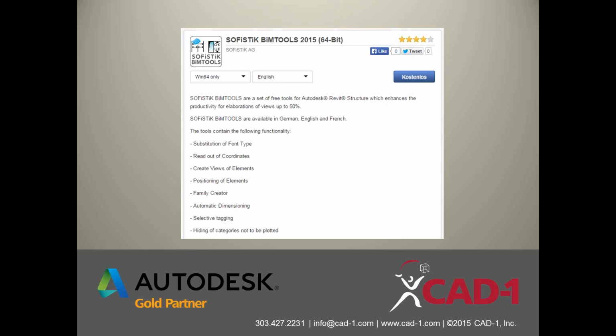So let's just face it, I'm a residential architect. I like pretty fonts, and for me to go in and change all the tags, all the text, all the dimension styles, my elevations, my grids, that would take anywhere from about a day to 3 days. Typically, I was getting it done in about 2 days the first time around. It takes a long time to change all those fonts over.